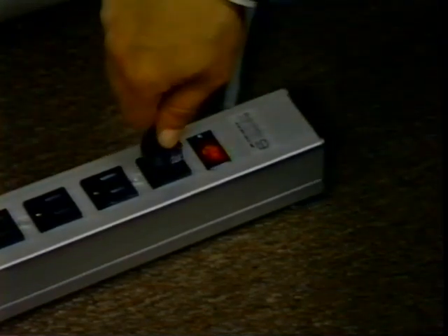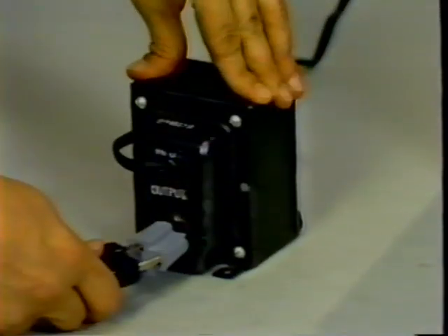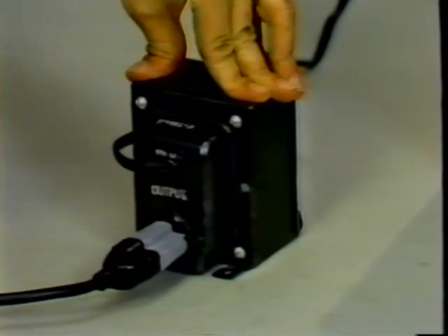The first step in checking any signal is to provide a proper ground point for the oscilloscope. Normally, you will connect your scope to a 3-prong grounded outlet and apply AC power to the unit under test through an isolation transformer. The probe's ground lead can then be attached to the chassis of the unit being tested. In this configuration, the oscilloscope provides a line ground to the unit under test.